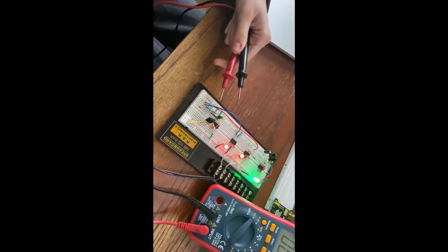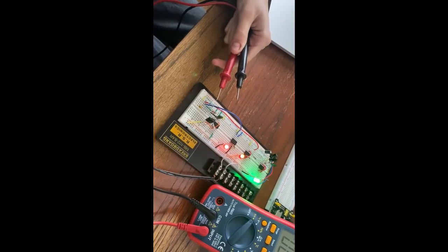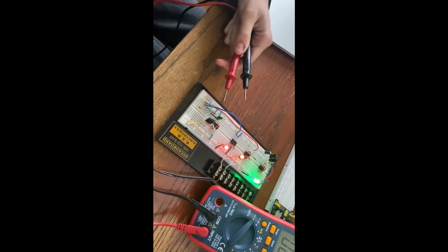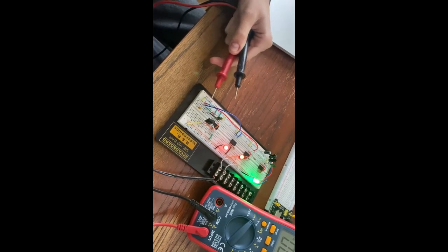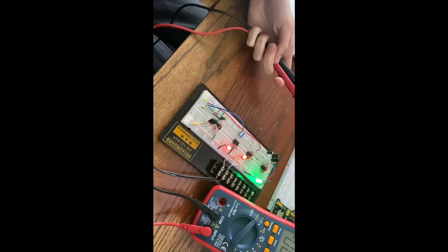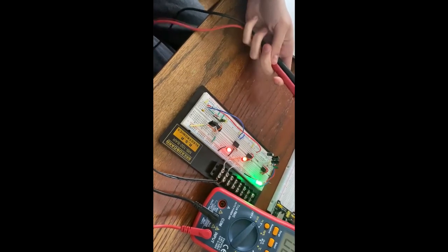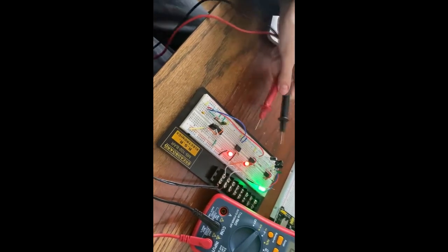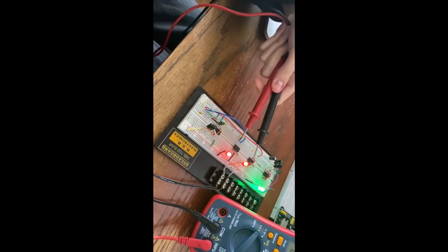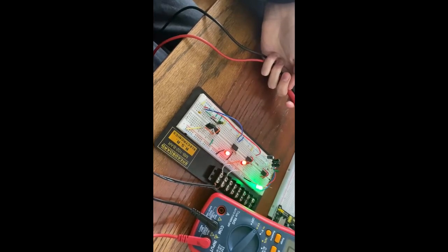With an LC resonant combo circuit at the output of a 555 timer right here, with capacitor and inductor, I am modulating this waveform to produce a sinusoidal wave. This is the source signal that is applied to both the current and voltage sensors. With these red LED indicators, both of my current and voltage sensors are indicating that they are detecting a signal source at their inputs.